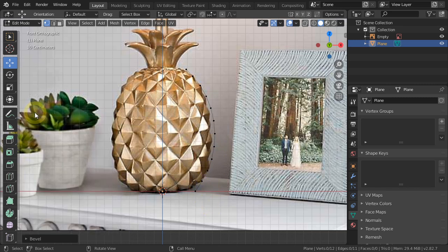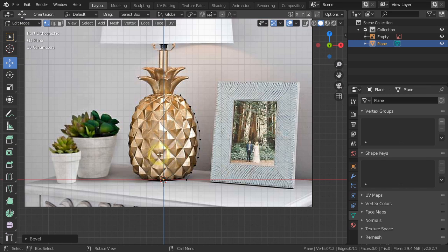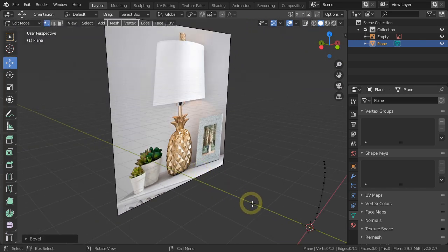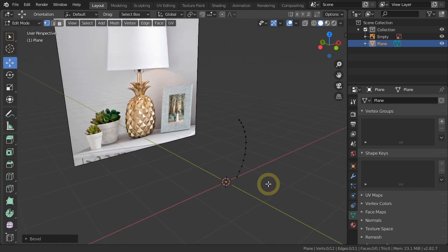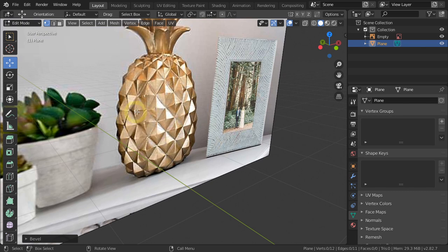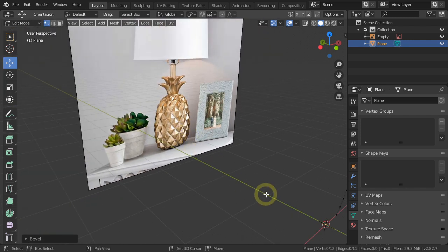Next, let's go back to the perspective view. We want to spin this profile and turn it into a 3D geometry. Just like before, we need to determine the number of side segments. From the reference image, we can see 6 diamond shapes, and each diamond shape needs 2 segments. So 6 multiplied by 2 equals 12. And if at a half area we need 12 segments, then for the whole circle we need 24 segments.